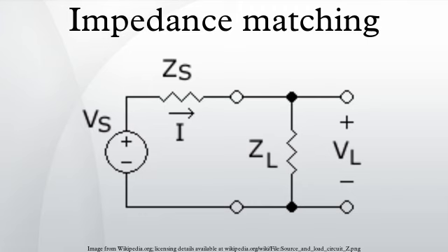This transformer converts a balanced signal from the antenna into an unbalanced signal. To match the impedances of both devices, both cables must be connected to a matching transformer with a turns ratio of 2. In this example, the 75 ohm cable is connected to the transformer side with fewer turns. The 300 ohm line is connected to the transformer side with more turns. The formula for calculating the transformer turns ratio for this example is given below. Resistive network.